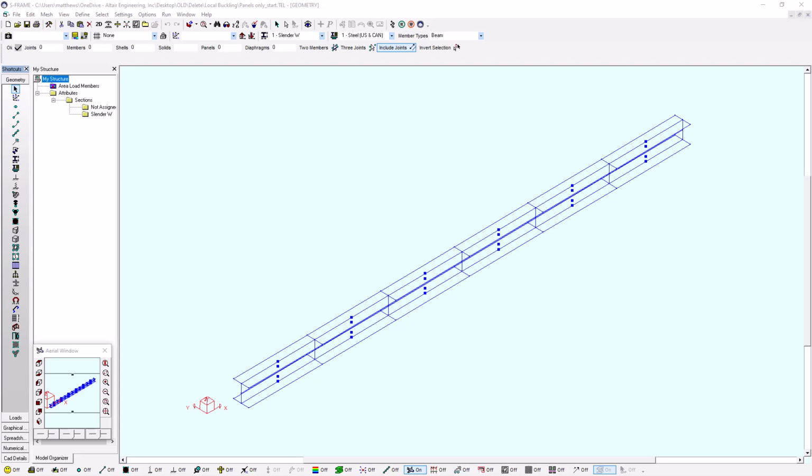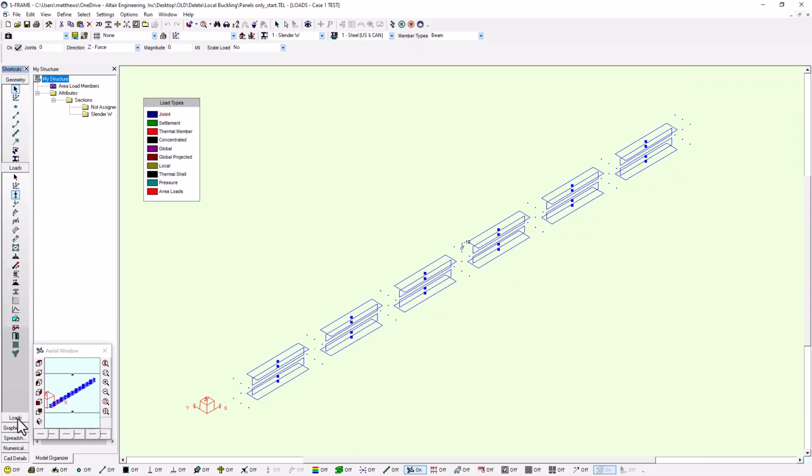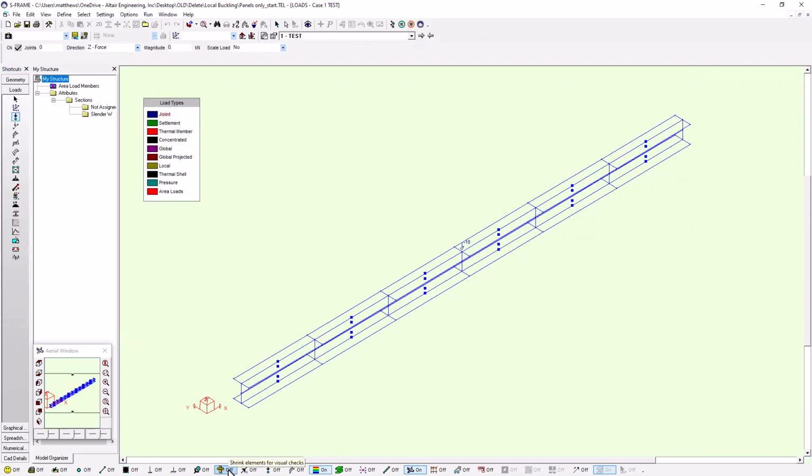So with that, let's just introduce the model a little bit more. You can see how we have a variety of meshable panels with different thicknesses that were automatically created based off of conversion from an existing member. And I've got a single load that's applied mid-span here, a 10 kilonewton load. And we're actually going to scale this up with the intention that we can evaluate it as it starts to approach the buckling limits of our elements.